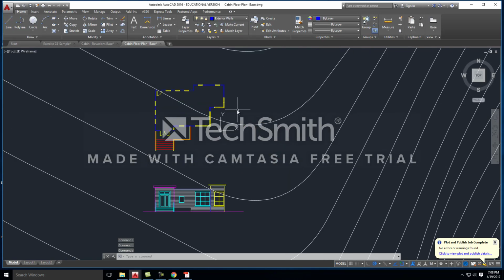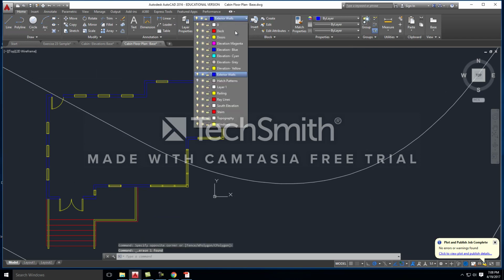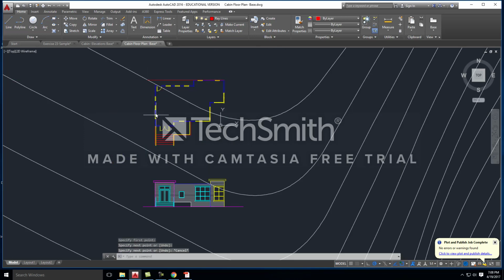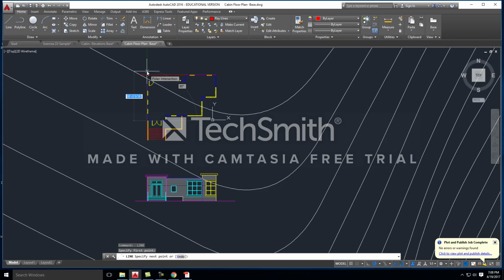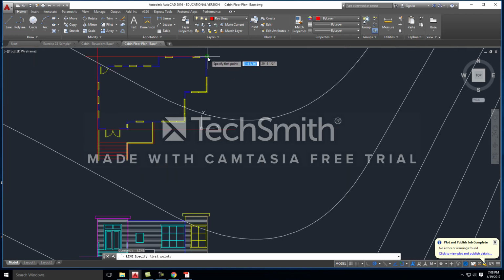Okay, and the next thing that I'm going to do is draw a box directly around my, wrong layer, around my building. All right, so I'm going to use my ray lines. These are all just reference lines. So I'm going to draw a box around my building, like so. I'm going to go ahead and just use the fillet command to close off my box.